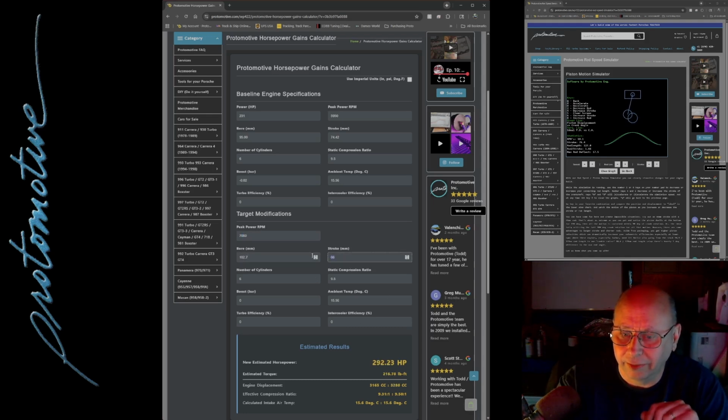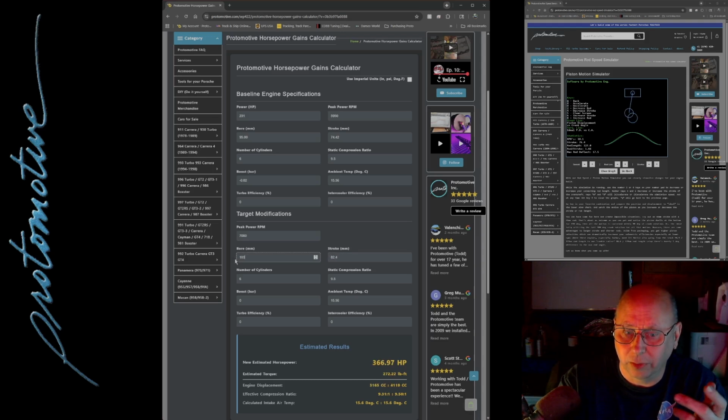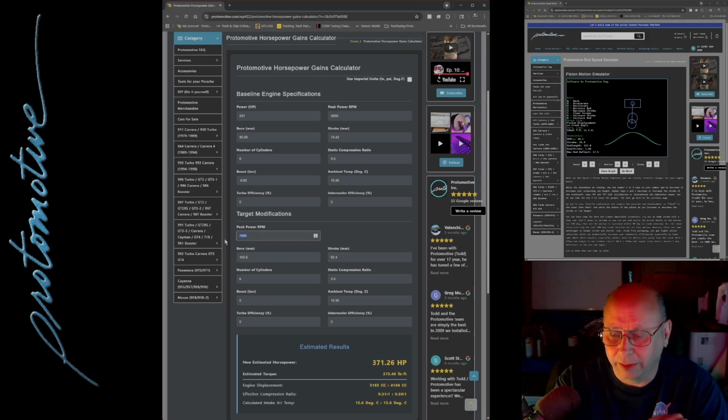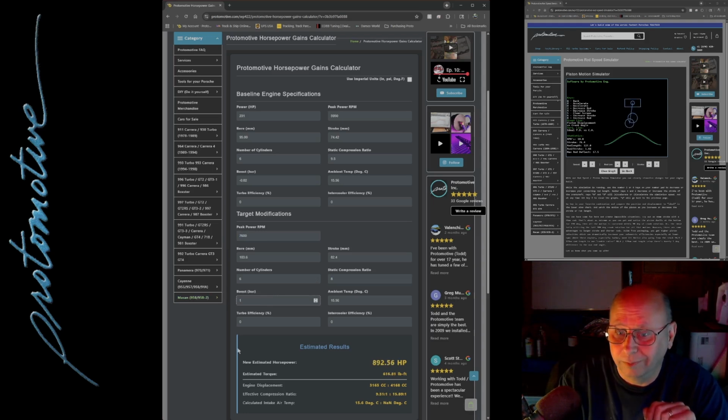102.7, we take it out to 82.4 even. We'll do a 4.1. Heck, yeah, our later ones are 103.6. Let's mimic a 4.2 liter 996 turbo engine running a GT3 intake manifold that makes peak power at 7,600 RPMs. We're at 8:1 compression ratio. Let's just put it at 1 bar boost only. Turbo's still around that. Really good intercooling.